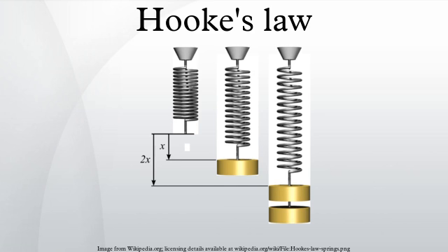The displacement x in this case is the deviation of the beam, measured in the transversal direction, relative to its unloaded shape. The law also applies when a stretched steel wire is twisted by pulling on a lever attached to one end. In this case the stress F can be taken as the force applied to the lever, and x as the distance traveled by it along its circular path. Or, equivalently, one can let F be the torque applied by the lever to the end of the wire, and x be the angle by which that end turns. In either case F is proportional to x.